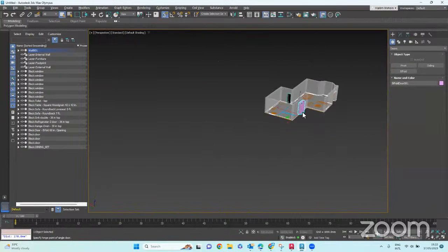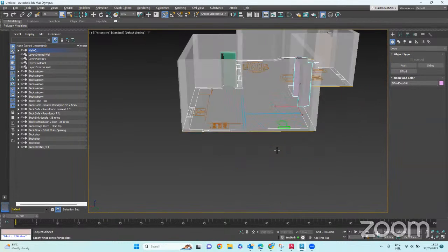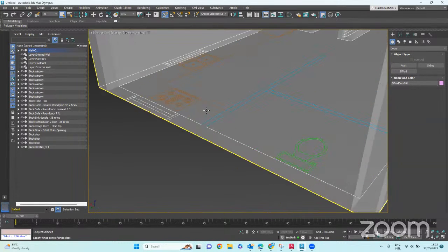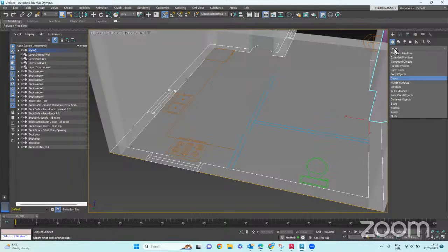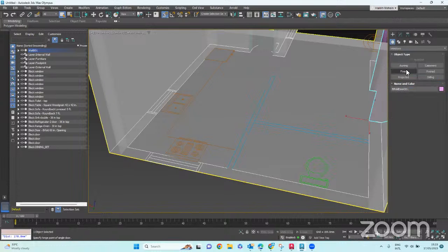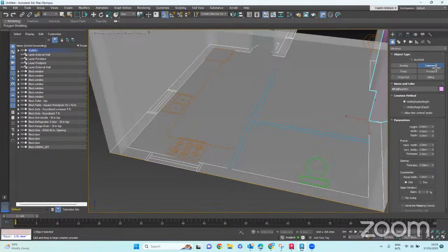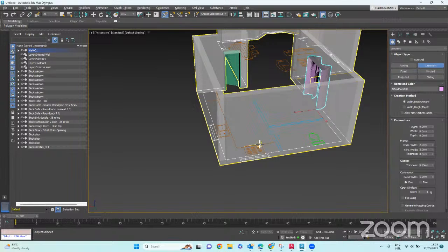So pretty simple. Next, I will also include how you create these windows, because it's pretty similar. What you have to do is still create in geometry, but instead of doors, you change to windows. For windows, basically we have 6 types of windows that you can do. For example, I'll just show you one of them. You take casement, because the methods are almost the same.